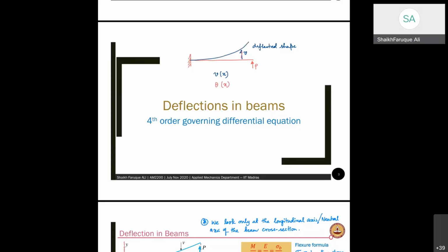One thing we have to do is to find a relationship between v and theta, and then find a relationship between theta and the load that is coming onto the structure, that is bending moment and shear force, capital V. And then finally we have to relate moment and capital V with the load that is acting on the structure. Either it will be omega or the P load that is there.